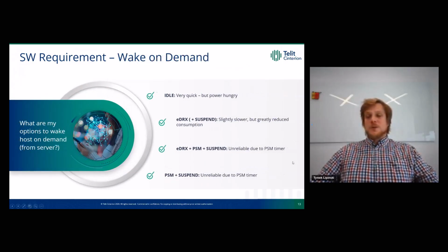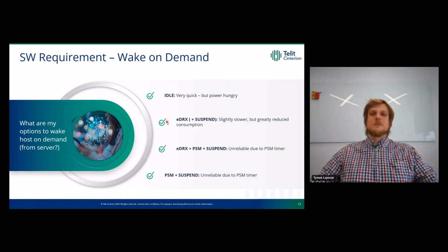What are my options to wake on demand? Of course, from the server. Idle, in short, very quick, but power hungry. eDRX and Suspend, slightly slower, but greatly reduced consumption. eDRX, PSM, and Suspend, the Telit Cinterion specific, becomes unreliable due to PSM timer.